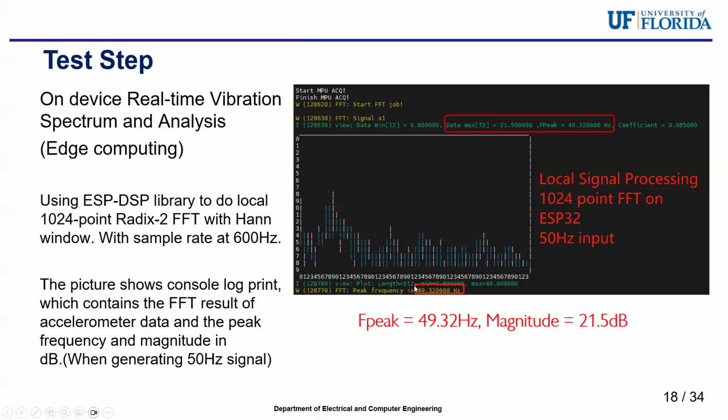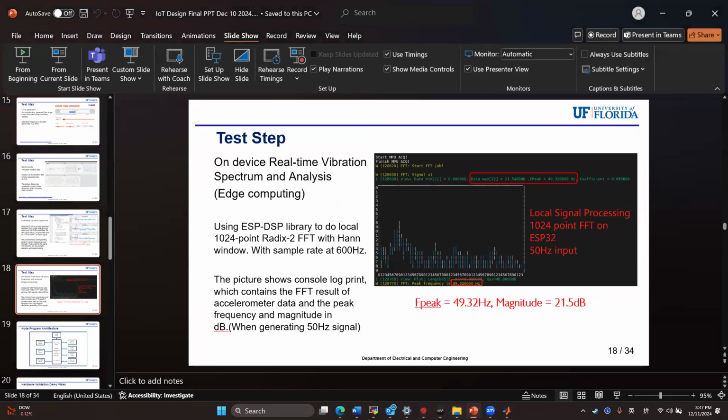Then I have implemented the FFT algorithm on the ESP32 natively to extract the frequency specification in real time and just upload them through MQTT protocol to our cloud. So now let me download the final version of our group project.